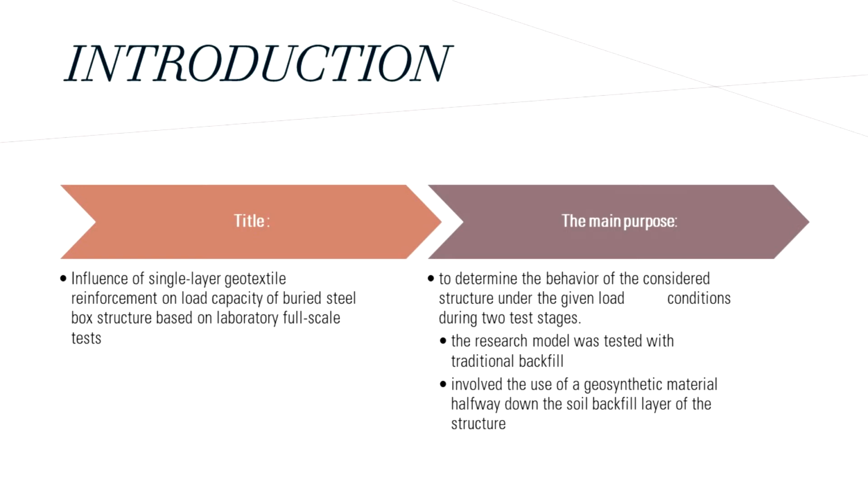The main purpose of our article is to determine the behavior of the considered structure under the given load condition during 2 test stages, where the research model was tested with traditional backfill and with the use of geosynthetic material halfway down the soil backfill layer of the structure.